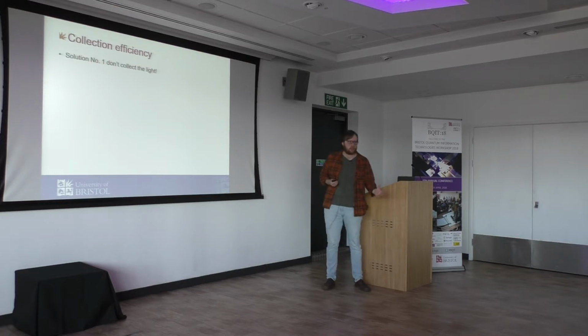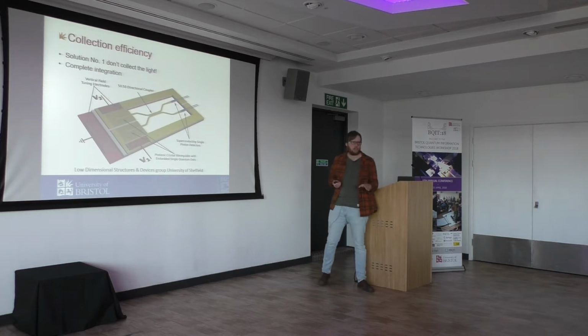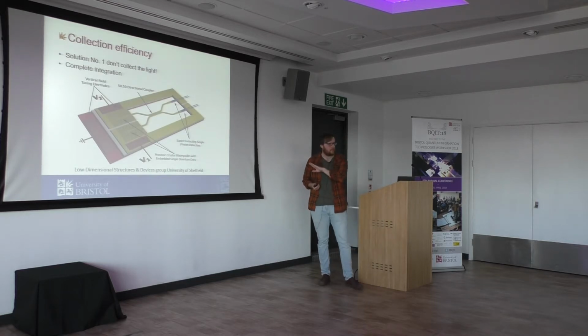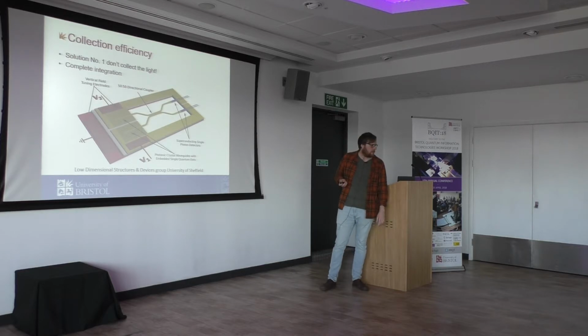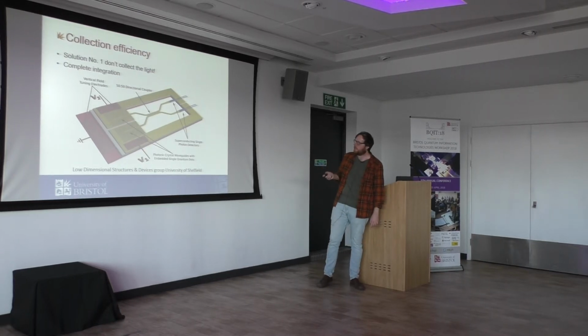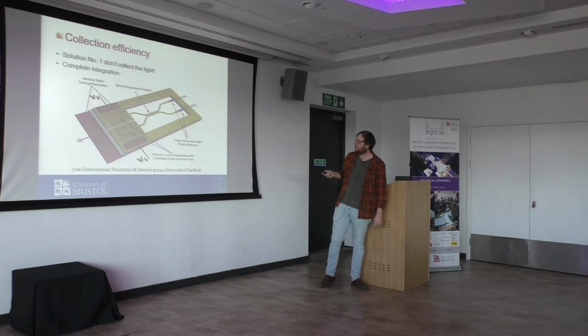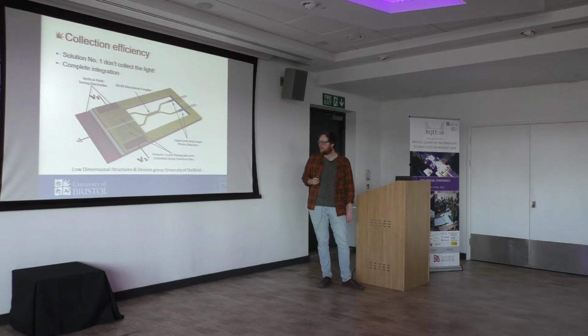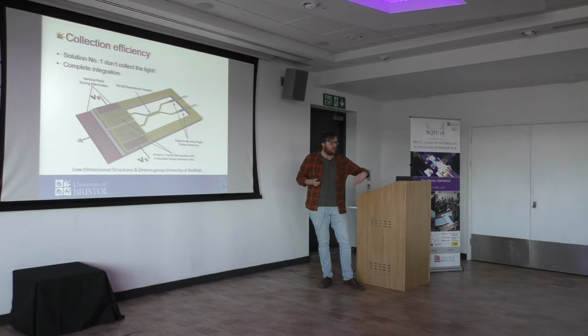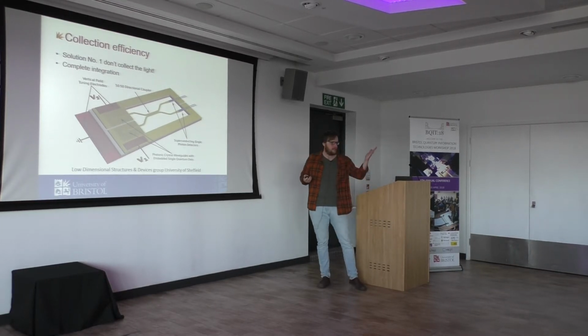One solution is just don't collect the light at all, which sounds very simple, but it's actually going to be complicated because it requires you to directly integrate everything onto one wafer. This example here I've lifted from the Sheffield website. They've got photonic crystal waveguides with quantum dots in them. They're directly linked into a linear optical circuit, in this case a 50-50 directional coupler, and the superconducting detectors are also integrated onto the architecture. So one way to solve the collection efficiency problem is do everything on chip and the light never has to leave.